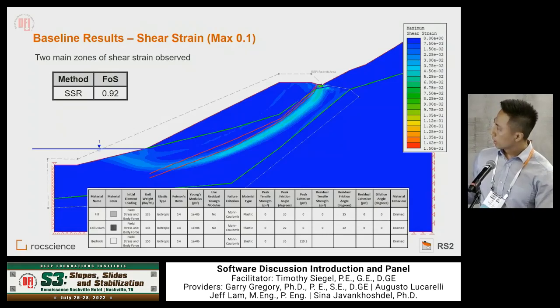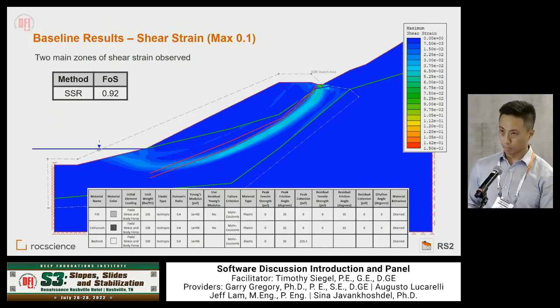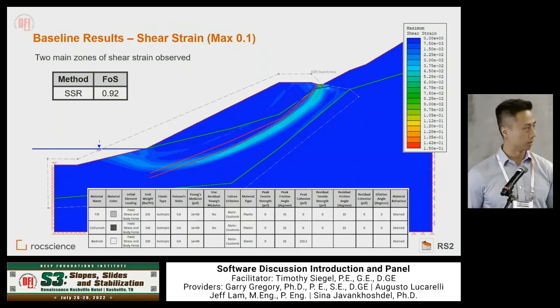And then we also noticed that in the fill material, the friction angle is 29 degrees. The slope is 22 degrees. So just based off of that, we knew that the target factor of safety of 1.5 was impossible, because if you do tan 22 over tan 29, you get 0.7 roughly. So we realized we have to just focus on the colluvium material. So our analysis is based off of that.